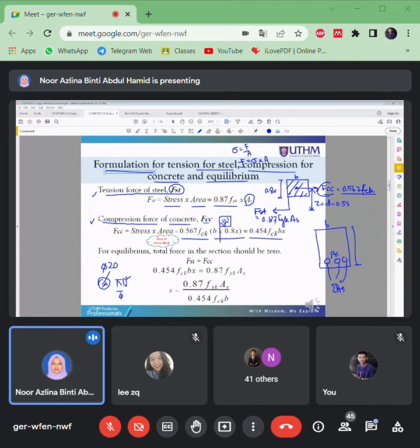If you don't want to calculate manually, there are tables. If you look in the Telegram group, I also attached the appendix. There you can also see the tables for the reinforcement bars. For one bar, the size can be size 6, 8, 10, and that gives you the area for that bar according to the diameter of the bar. So I proceed, okay?